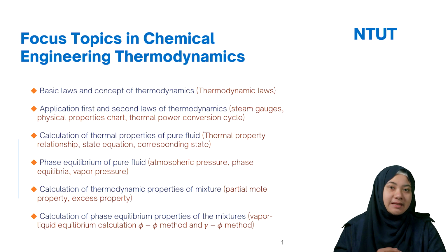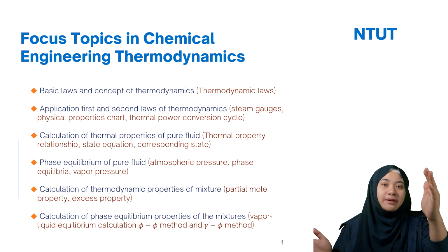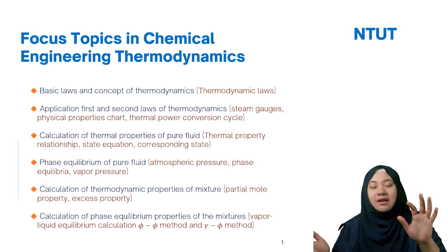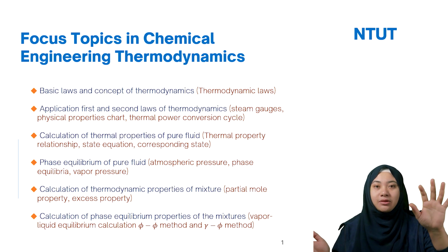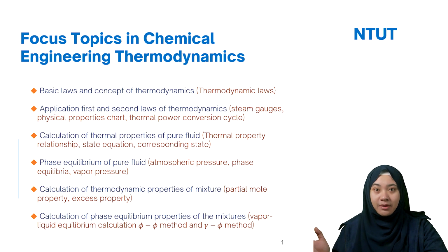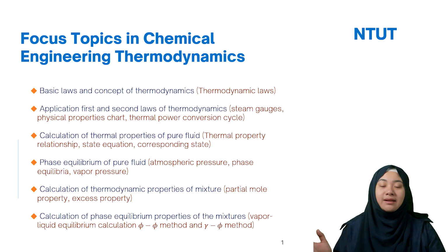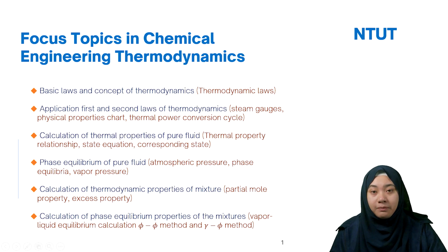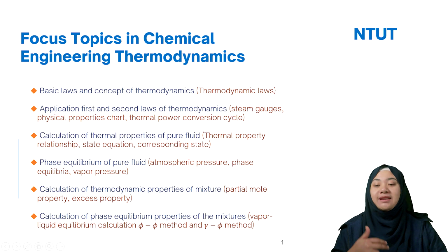So for distillation, you should operate at the bubble point, because you will boil the liquid, and then the vapor phase will go to the condenser to condense and to produce the product, and the other is in the reboiler. The less volatile components will stay in the bottom, because they cannot evaporate. So here you need the phase equilibria of the pure fluids, especially if you have two compounds, you need the phase equilibria of the two liquids.